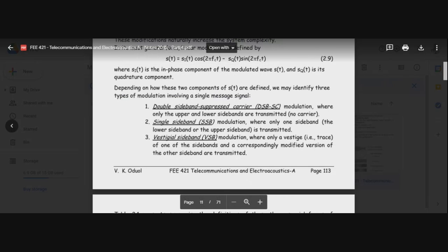You can have a double sideband suppressed carrier that will get rid of the carrier, so you can use the power in the carrier to carry a message. Single sideband will deal with the wastefulness of bandwidth, reclaiming the other half of the bandwidth that is being used but is just repeating what is already in one half of the band.